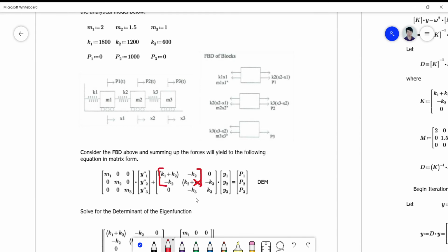While if you expand it into a third degree of freedom, you will notice that the simple modification is that you add up to a K2 plus K3 and then a K3 there will end the last element of the matrix. And of course your negative K2 and negative K3 take care of the symmetric pattern of your K matrix. No?